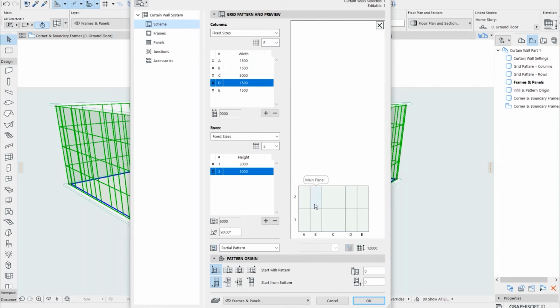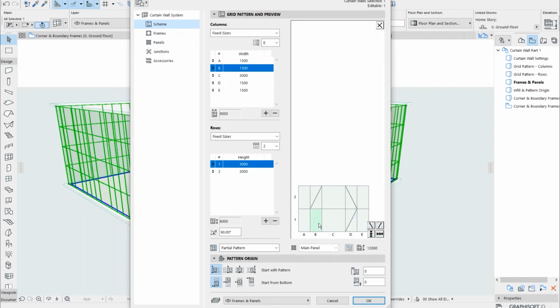So now I'm going to create a hexagonal panel here. For that, I'm choosing this particular panel. If you see here, I have the add crossing frame option when I select the panel, so I can just create a crossing frame. Okay, so in order to create a hexagonal pattern, I'm choosing these four, and then I'm creating the panel. Now I'm able to select these panels individually because I've split them into two by creating a cross frame in between.